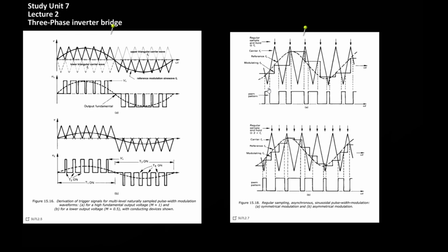The more modern approach is to harness the advantages which come with any form of digital control, where this type of natural sampling will be formed with analog circuitry. A more regular sampling scheme can be implemented with a fully digital implementation. So in the digital case, the sampling period is determined by the controller, or DSP or FPGA, whatever it may be, and the sinusoid is generated from a memory bank of points which represent different amplitudes on the sinusoid.